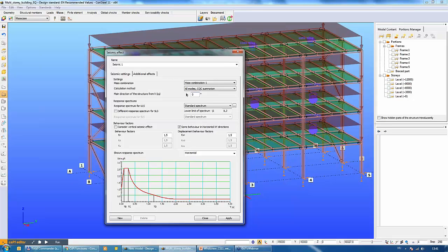By default, the main Q1 direction is parallel with the global x-axis. We can set the directions with 2 points with this black arrow button, or we can set the angle of the main directions from the X direction.